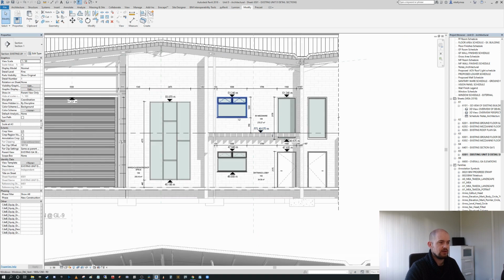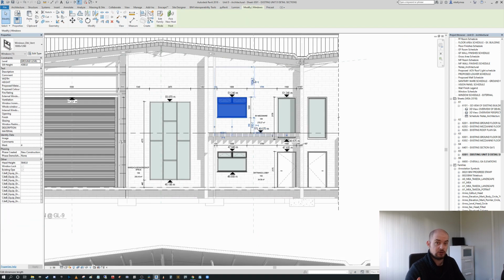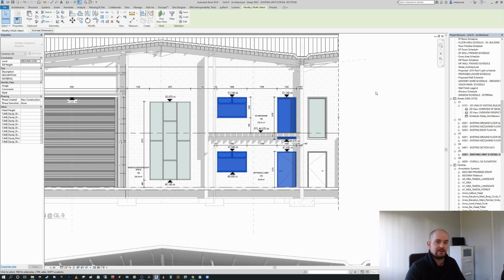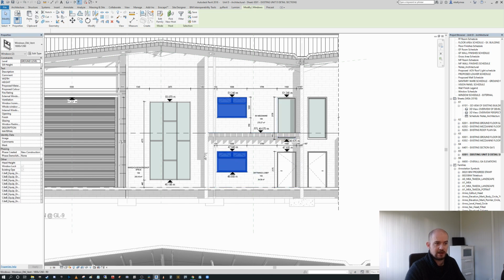So what we actually need to do in Revit is, if we select the first item, we need to press Control, and you will see that you get a little plus on the cursor, and then you can select your next elements, and that will continuously add to your collective selection. Okay, and similarly, if we want to subtract, we press Shift, and we'll see a little minus beside the cursor, as you can see, and we can simply deselect the elements that we don't want. Okay, so that is fundamentally the most primitive but the most used way of making selections in Revit. So that was number 10 on how to use the common selection methods in Revit.